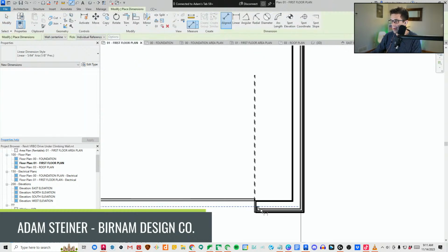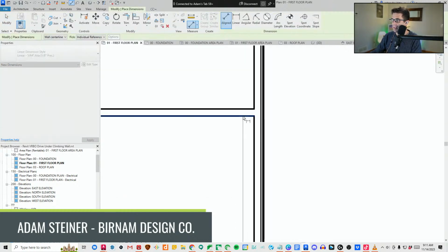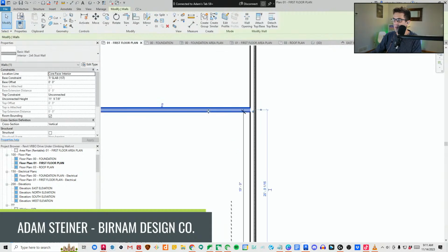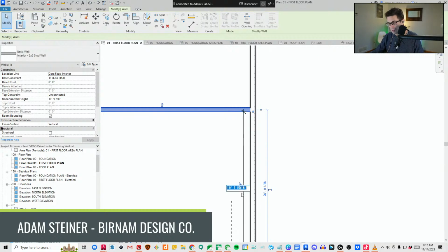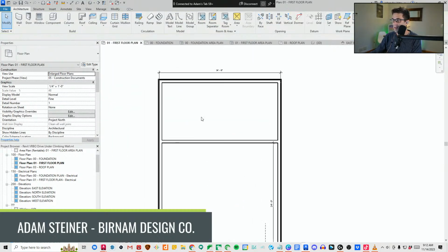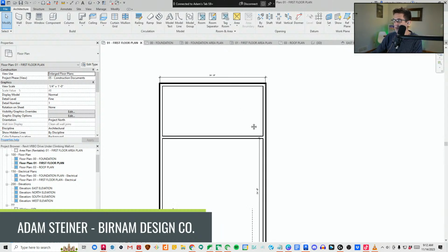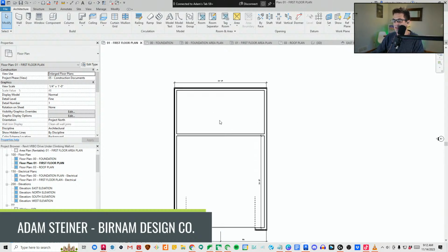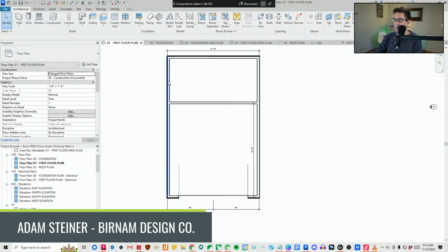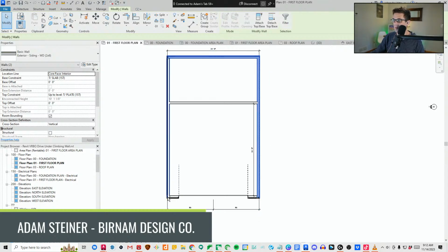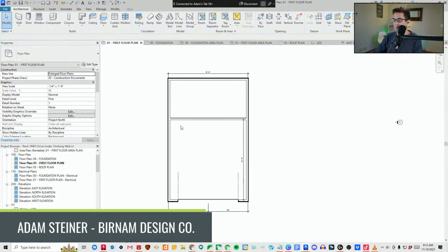Interior stud wall, we want that garage to be a good depth. Let's go 24 with it. Okay. That's not leaving us a lot of room for our climbing space here and stairs up and all that. Maybe, actually these walls, this is going to be a simple box, so all these walls are going to be 2-story. So we're actually going to go to top of plate second. Okay.